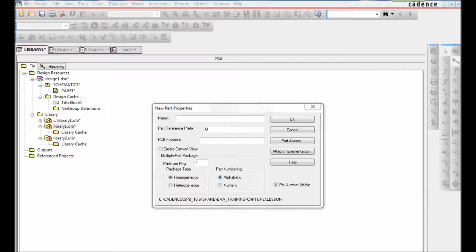Thanks. So this is really just an intro to the actual lab, but I thought I'd go through this. So there's the part editor tool palette. What I have open here is the new part properties. When you OK the new part properties dialog box, the capture tool opens the part editor. Part editor tool palette is located on the right side of the capture window. It contains tools used to create the edit part bodies. The following table describes each part editor tool palette button.